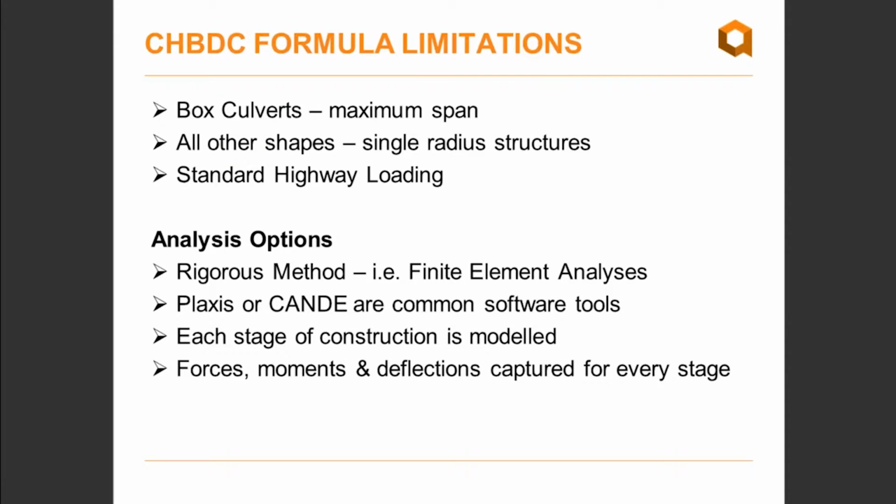It is important to note that all the equations in the CHBDC were developed through finite element analyses for a limited range of sizes and loading conditions. So beyond these limitations, the code will permit the use of rigorous methods of analysis such as finite element modeling in order to capture what the code equations do not capture.